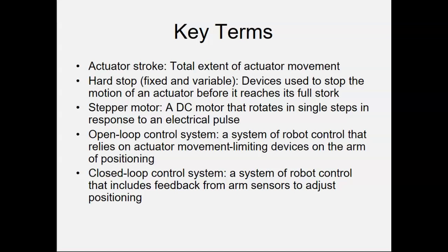Hard stops are for robots that, I don't remember the term, nothing else but the term servo motor. Okay? So the whole purpose of a hard stop is to make sure that the robot can't do something like a 360. These guys have hard stops as well as program stops. What that means is that you can only go so far before the robot sits there and goes, no, I'm not supposed to be here. Nope, you can't move me into this space. And the whole purpose of that is to protect the internal workings of these.